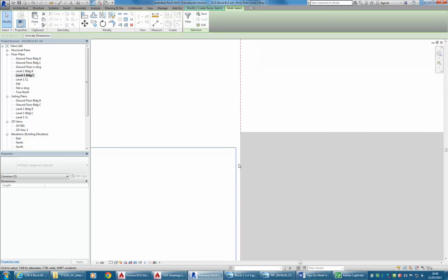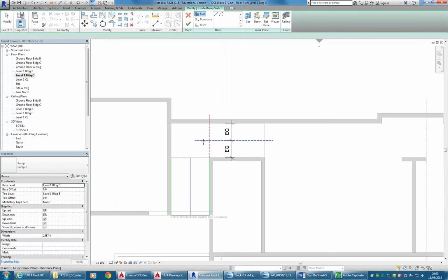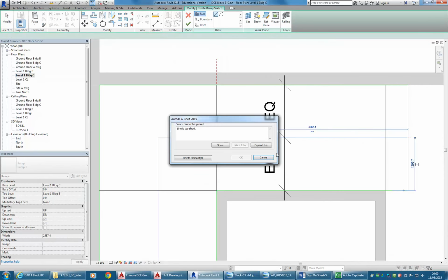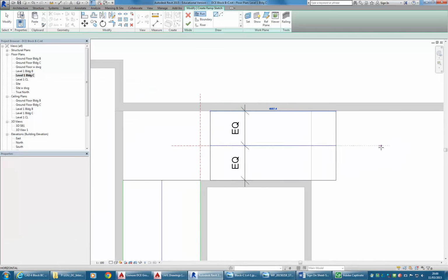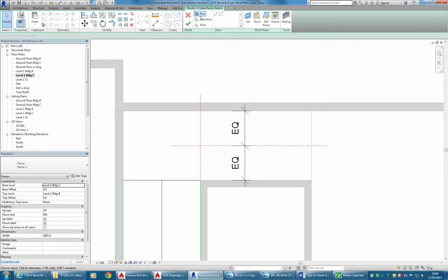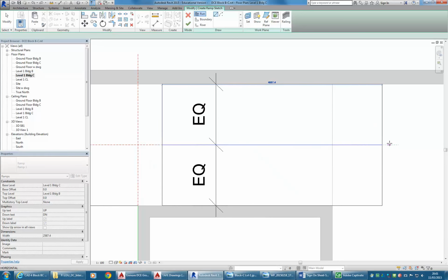It's all to do with the way it makes landings basically. Nope. Okay, just to test it out, I'll do one further away. And yeah, okay, so that's worked. And that's actually a good workaround. So what I've done there is just using the run tool still, draw it over the reference plane that I want it centered on, but starting away from the intersection.